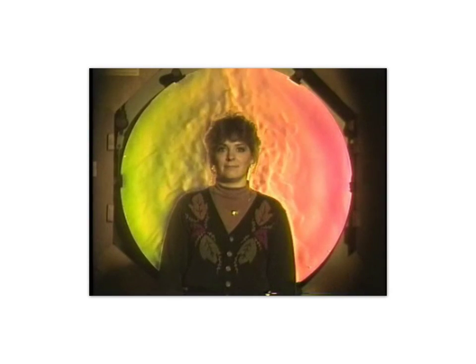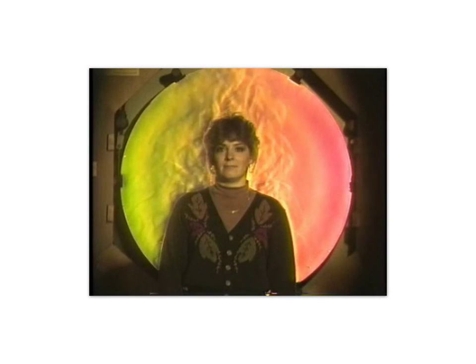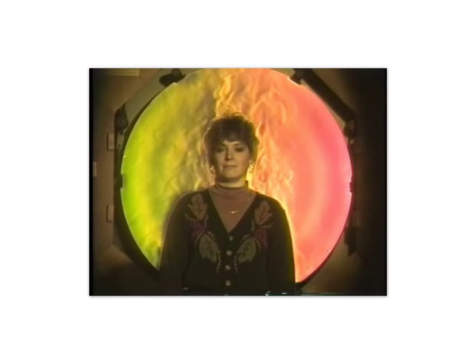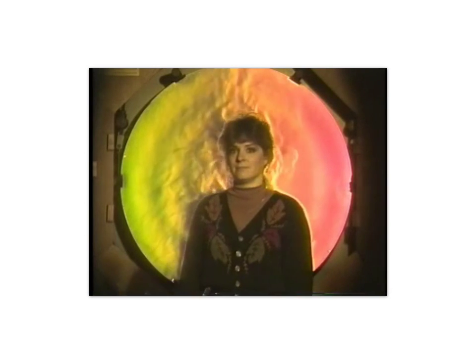Another major category of flow visualization is optical methods. Typically, a beam of light is passed through the flow, and parts of the beam are refracted due to flow disturbances. The disturbance in this case is the heat shed by the human body, which creates a warm, turbulent plume, the human thermal plume. The subject is standing in front of a precise parabolic telescope mirror 1 meter in diameter, big enough to be the centerpiece of an astronomical observatory. Instead, it's actually the centerpiece of a Schlieren optical system, a laboratory technique for visualizing density differences in transparent media.